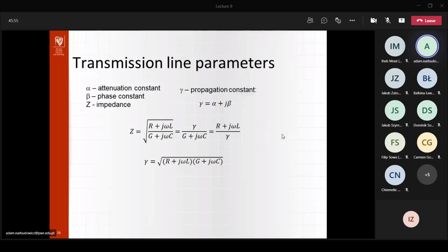And this is very helpful to us, because most of the transmission lines we want to design as non-lossy lines, or to have as little losses as possible. So we hope to have cables or transmission lines which are simply the square root of L divided by C.